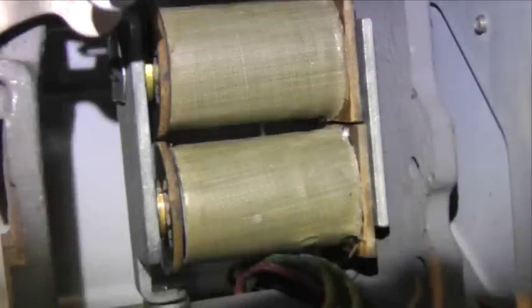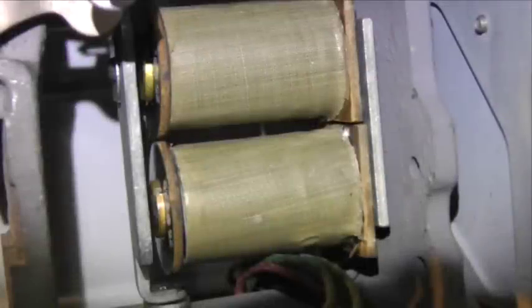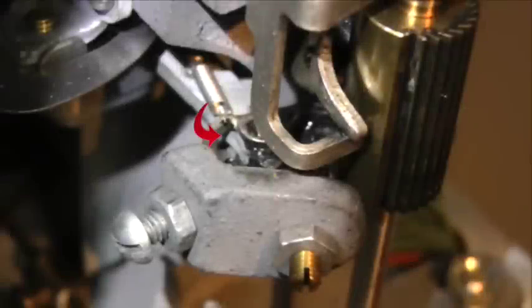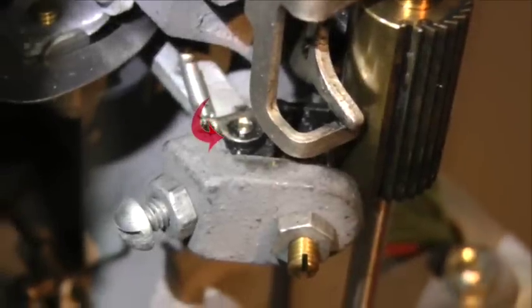This releases the rotary armature, and its attached pawl disengages from the rotary ratchet. The operation of the A relay also de-energizes the windings of the E relay, and after its slow release interval has lapsed, it releases.